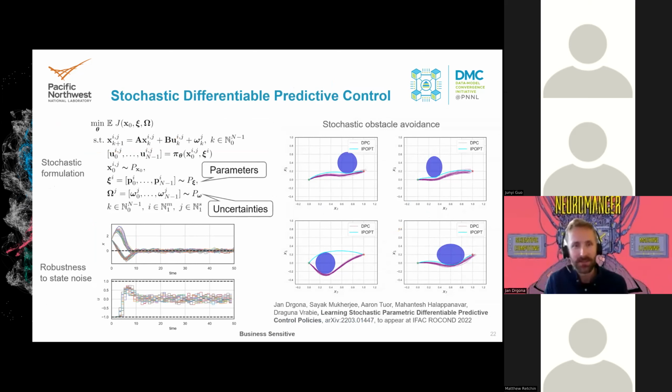Then we have been expanding this to include some uncertainties. The idea is simple: just orthogonally sample some perturbations of the system dynamics that can be additive or can perturb some parameters of the system dynamics model, and train it offline again. This is a little bit more expensive for the offline case because of the more samples that are required during training, but then upon deployment, you can be way more robust and satisfy the stabilization task or this obstacle avoidance with a parametric obstacle subject to perturbations.